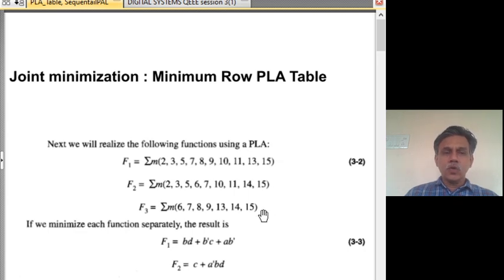So if you use a K-map reduction technique and reduce f1, f2, f3, this is the result that you would get. Whereas this is the minimal expression for f1, that is the same as this canonical expression, where we have individually minimized the K-map corresponding to f1 and obtained this reduced SOP. Similarly, for f2, we have obtained a minimal expression which is given here, and so on. In fact, I am not showing these individual reductions, but if you do that, this is what you would get.